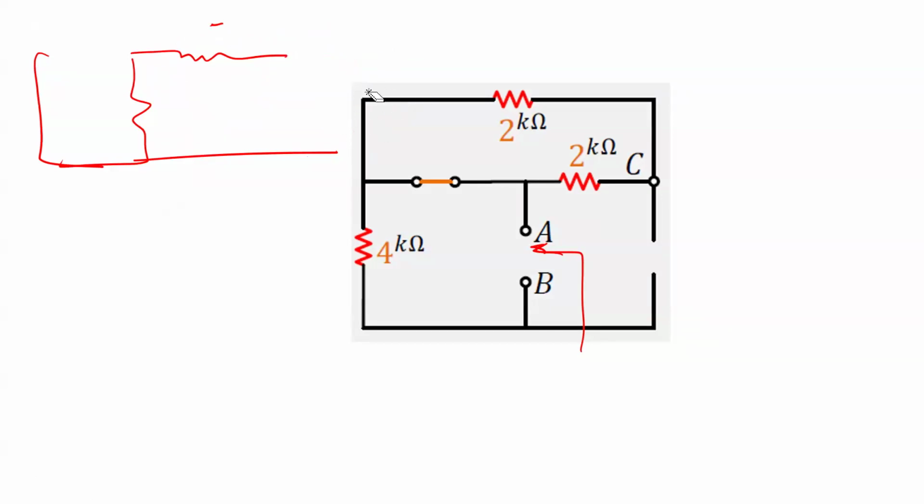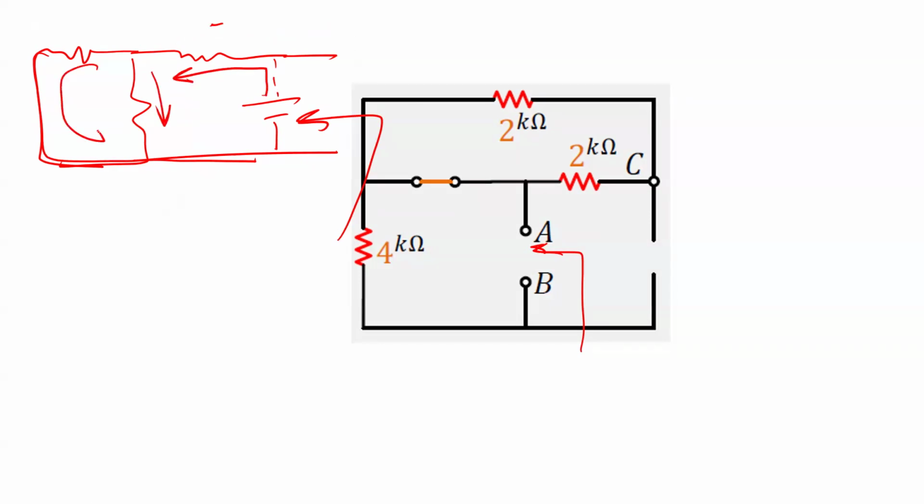Again, guys, I'm not sure if this is difficult or not. But again, in one example, we had a circuit like this one. I told you I want to calculate the equivalent resistance when I look this way. Okay. So what does this mean? It means if you connect a source this way, a battery, a voltage source, whatever it is, what resistance will this battery see? The way you have to think about it, you will give current this way, and then this current is split between these two.